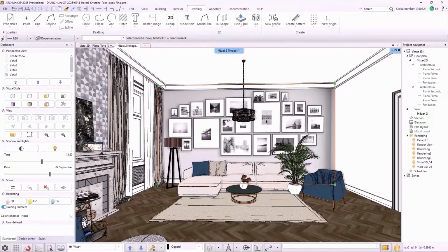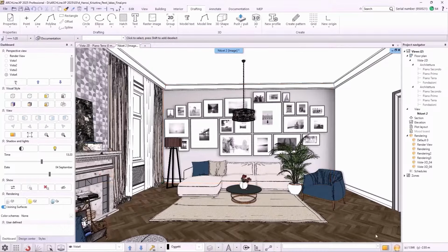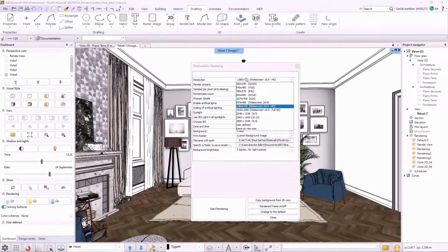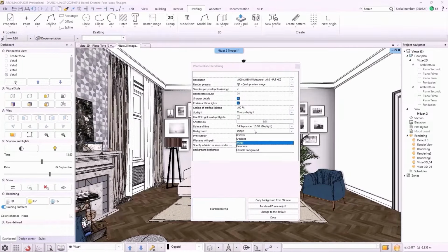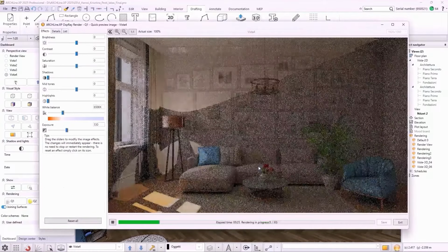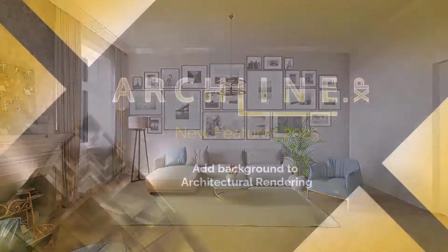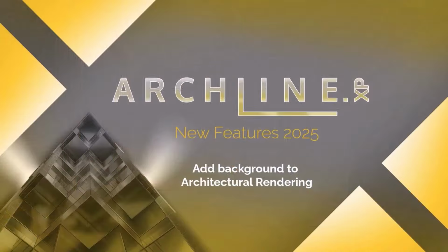It is not a problem if the area is not defined perfectly, or you change your mind about how it should look. In this case, I wanted to make sure that the wall edges are aligned, so I adjust the perimeter of the picture again to make sure everything looks perfect. Set the new corner points in the picture and align the wall edges with the actual walls to get the best result. Start the rendering and impress your clients with world-class pictures of the spaces you designed for them. As you can see, there is no need to add the picture as a 3D object one by one. This method gives a perfect result as well.